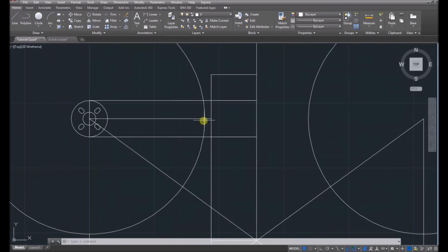Okay, now for the arms, sometimes what I'll do is I will go to the arc tool, and I'll go to this start end angle arc. There are heaps of different ways of doing it, as you can see, but I like this one. You click on your first point, you click on your second point, and now you can create an arc. Just to thin the arms out in the middle a little bit, save a bit of weight, make it look a little bit better. Now I usually eyeball it, but then look at the degrees and actually type in the degrees that I want.